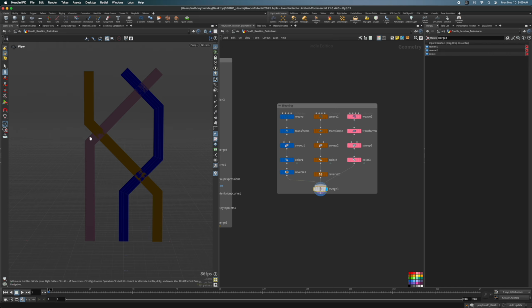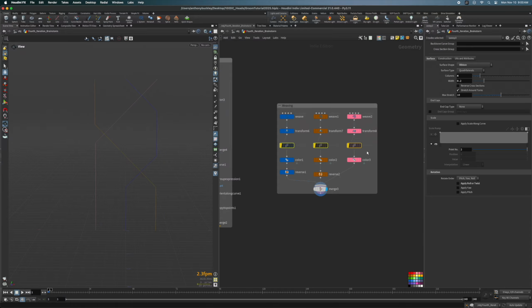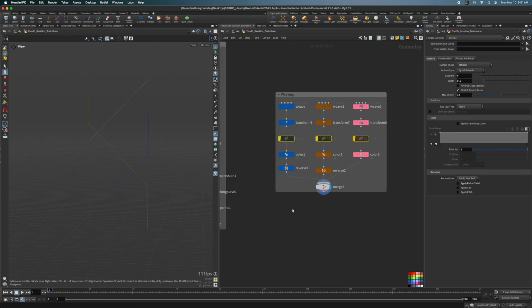This is the pattern that we want to try to create with a braid. To move forward, to cross once while the third strand does not cross, and then to move forward on the outside again, diagonal to cross again. And as we repeat this crossing pattern with this weave, and then reassign these lines, turning off the sweep, and reassign these lines as input curves for hair generation, we can use the L system, which can be recursively referenced using generations, to grow this pattern repeatedly as a braid, as you will see in the next final iteration, the fourth. I hope this helped you to understand the basics of some of the commands for L systems, and thank you for watching.